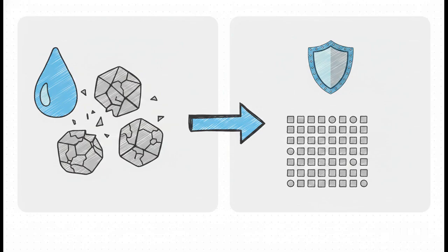On the flip side, we have magnesia. Magnesia acts like a strict bouncer. It segregates to the grain boundaries and locks them in place, inhibiting grain growth so the material reaches full density while keeping a really tight, fine-grained structure.